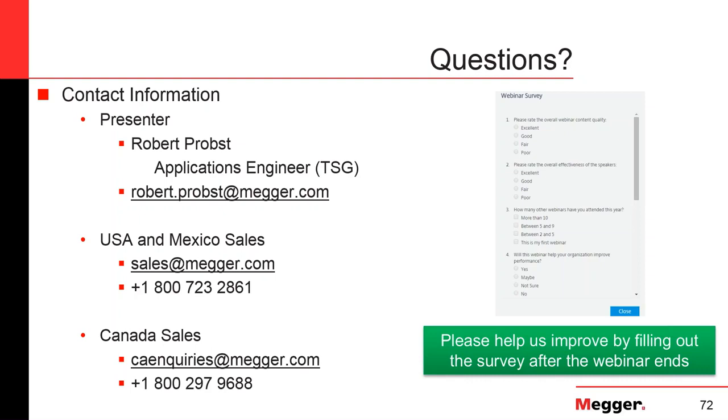And as John said, less than 30 volts. A lot of testers are 6 volts, 12 volts, 15 volts in that range. So, I mean, don't do it, but technically you could touch that. You can run 10 kA, you can touch it, and it won't hurt you. It is low voltage, high current. That's the trade-off. And this is why the burdening of the source that I tried to explain with the circuit impedance is such an important thing, because your output voltage is 6 volts. If you consume 5 volts of that just because of leads and inductive loop and voltage drop, there's not much capacity left to drive a high current through that load.